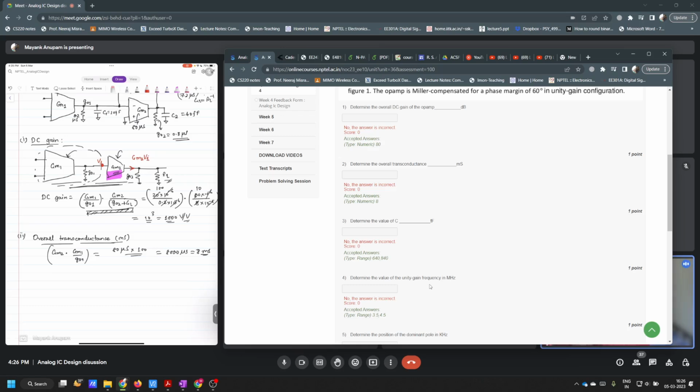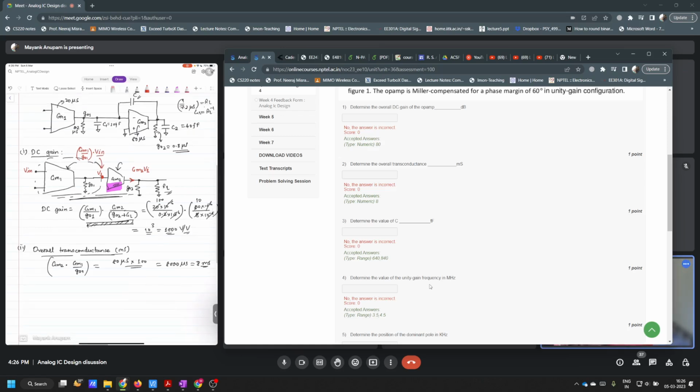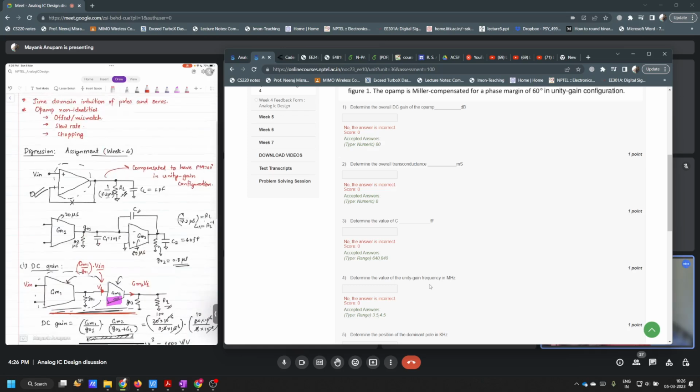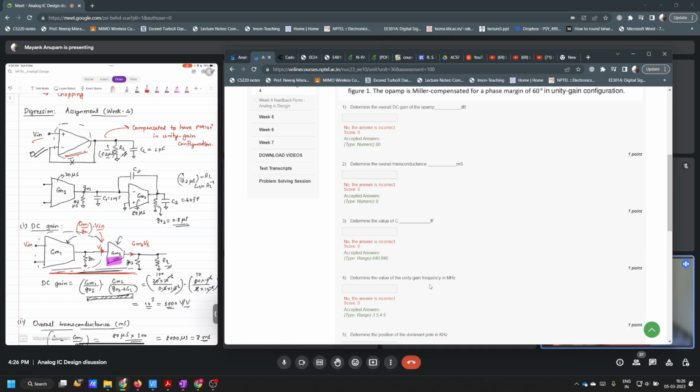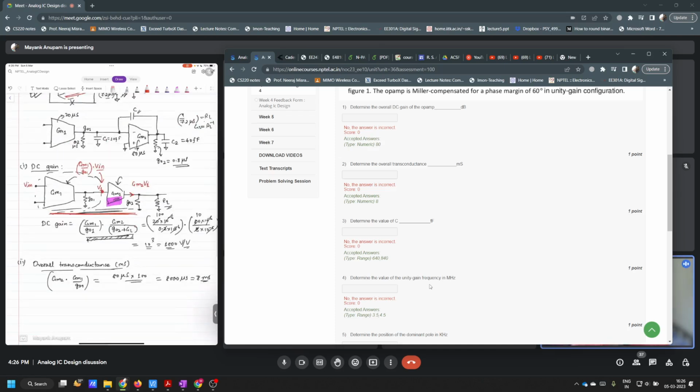And this voltage V1, what will it be equal to? This voltage V1 will be equal to GM1 divided by small GO1, into whatever we apply here, V in. Correct. So if you view this whole two-stage Miller compensated op amp as a single block, as presented here, then when you apply an input V in, the current that will be pushed out will correspond to a GM which is amplified by this factor, isn't it?